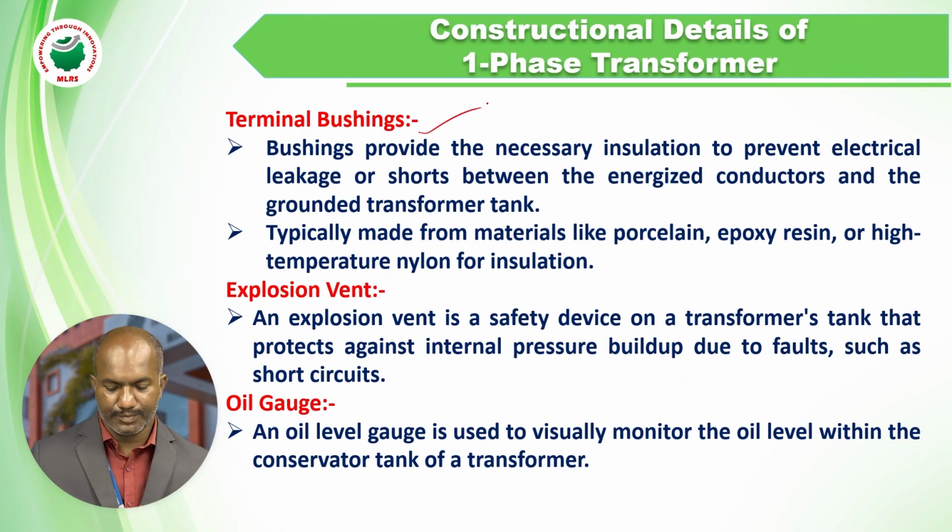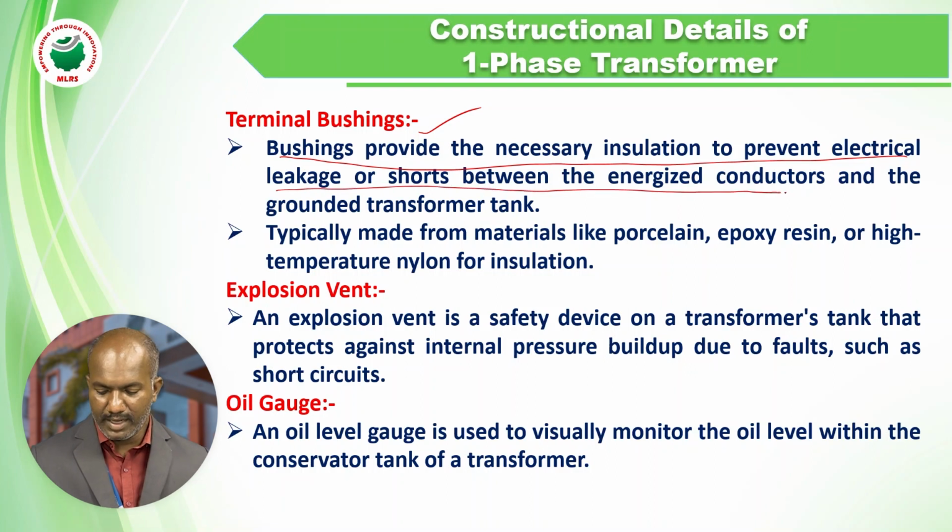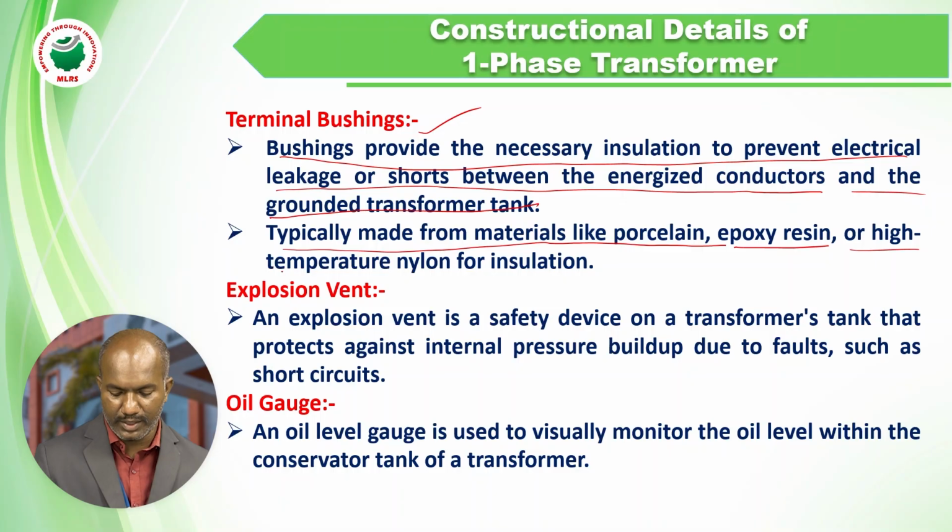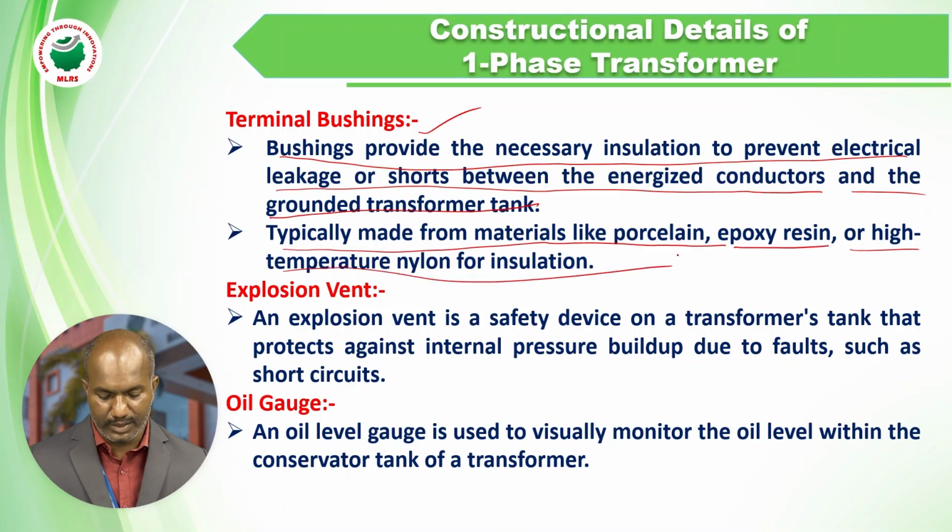Terminal bushings. What is the duty? Terminal bushings provide the necessary insulation to prevent electrical leakage or shorts between energized conductors and the ground, that is the transformer tank, typically made from materials like porcelain, epoxy resin, or high temperature nylon for insulation.